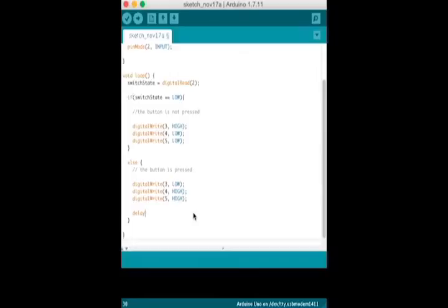So build your spaceship digital write. You've told the Arduino what to do when the switch is open. Now define what happens when the switch is closed. The if statement has an optional else component that allows for something to happen if the original condition is not met. In this case, since you checked to see if the switch was low, write code for high condition after the else statement. Okay, done that.